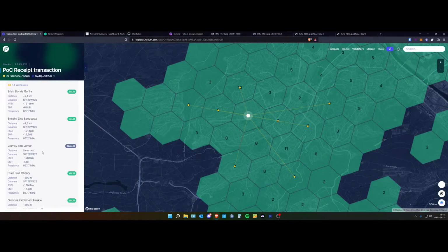Even if you say something like you're living in a not so crowded area and you're trying to reach as far as you can, always try to get as high as possible and use a high dBi antenna, or even some of those really high dBi antennas, 14 dBi plus, and try to face this directly into a city. Sure, you can do this.